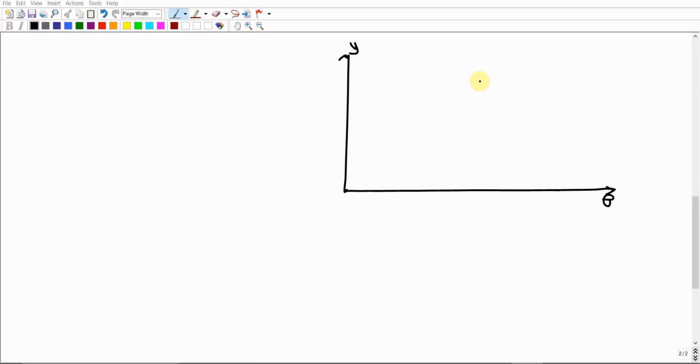Why 12 centimeters? Because, as we discussed in the previous meeting, the cam should be rotating 360 degrees as the angle of rotation, right? And if we assume the scale for this angle, like every 30 degrees of the cam rotation is equivalent to 1 centimeter of the drawing scale. So in this case, 360 divided by 30 gives us 12 centimeters. And this is what we're gonna do.